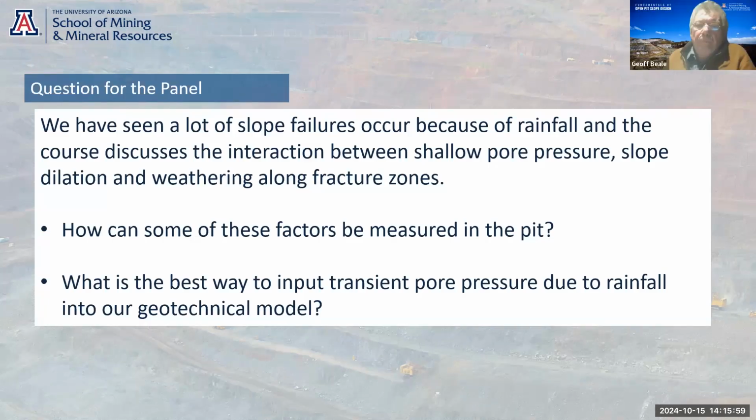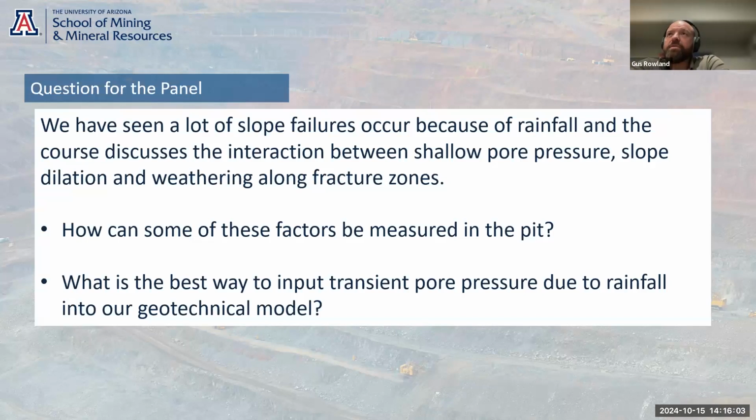Yeah, I think that's a good point as well, that there's sometimes a tendency to use the sensitivity analysis of RU as kind of the end of the line and then not go back and look at it after the fact. And so using those observations to sense check what you've seen with your sensitivity analysis is important. And as Blair said, you want to make sure that you're linking that to real values and getting an understanding of how your RU relates to an actual pore pressure elevation or a phreatic surface.